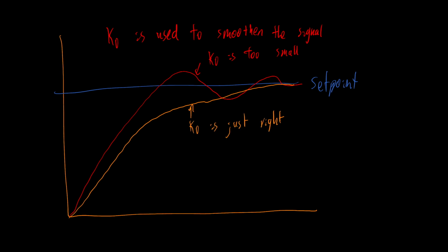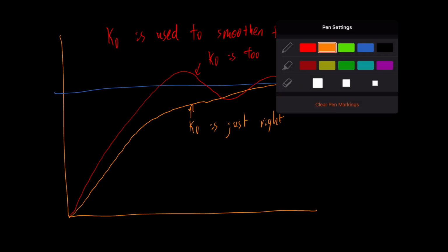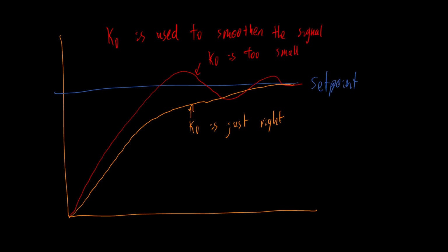Now remember that increasing Kd actually dampens your system, so it will slow down. Now if Kd is too massive, remember Kd becomes quite aggressive to rates of change in error. So if there's high frequency noise or anything like that, Kd starts to act erratically, and it also acts erratically to the overshoot. So you'll find this weird oscillatory behavior.